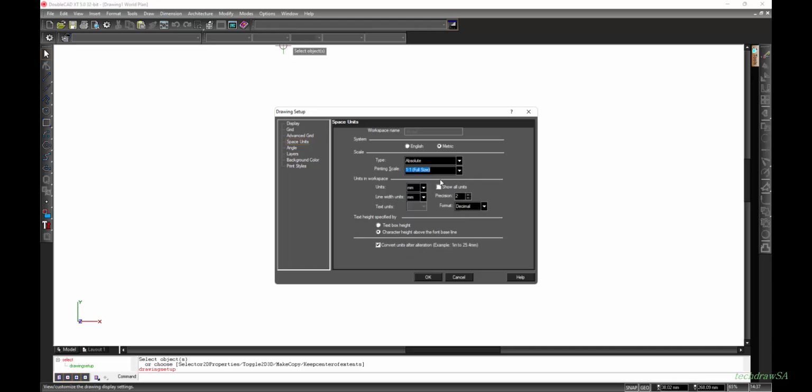But for what it's worth, I am just going to use the 1:1 full scale because obviously I want to print this out on an A3 page where the scale is accurate, and I know I have set up my layout of my A3 page correctly. And then another thing that's important is that we are using millimeters in the metric system, obviously, and then everything must be millimeters.